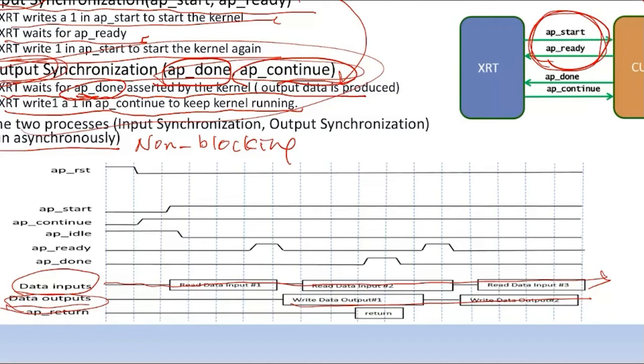So for every bus, for every resource, you want to design it in a way that they are all fully utilized, like the DRAM bus. If you see the DRAM bus only has 50% utilization, then you should push the DRAM utilization to 100%. If it cannot achieve 100%, then maybe the data supply or data consumption is not fast enough, meaning your computation is not done fast enough. Then you push your computation.